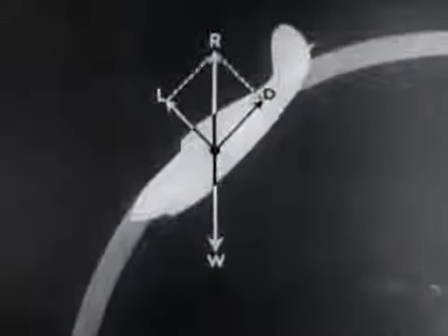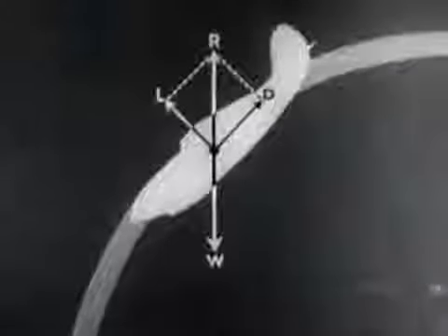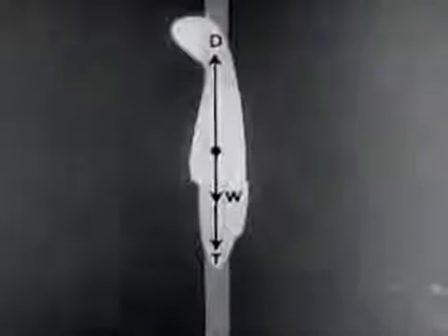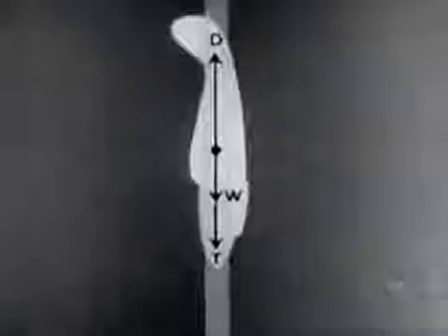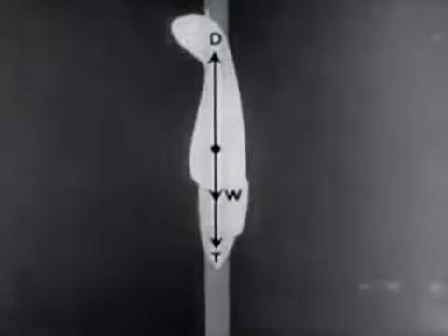increases. Lift decreases, since in this attitude the weight of the airplane is opposed by the resultant of lift and drag. As the flight approaches the vertical, speed increases until the terminal velocity is reached in the so-called vertical dive. In this condition, lift is zero, and the weight of the airplane plus its thrust are opposed by drag alone.